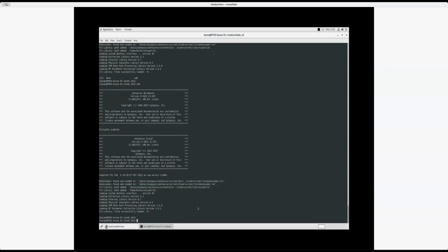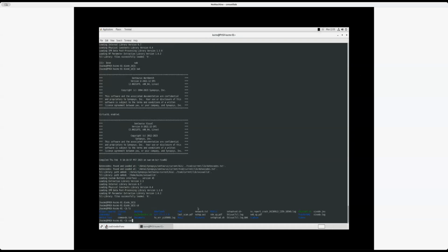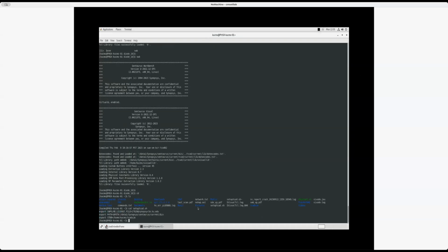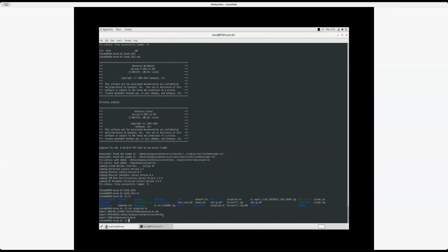Good. Okay. So I have a PC here where I have, a bit like you did, the local installation of the TCAD software. And usually I always set things up like that. So I have a little setup script, a bash script. And then there's essentially 3 lines you need to start the software. You need to know where the binaries are, so wherever the tool is on that machine that you mentioned, if they have the tools already, there's probably a folder, and you just need to know where the binary is. It doesn't have to be a folder that you can write in.